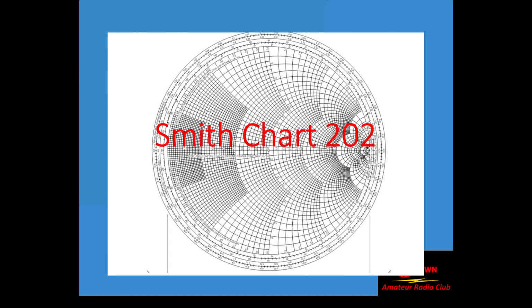So I guess the question is more theoretical, but is that 65 watts or whatever, is that being radiated, or is that just between the antenna and the stub? It's between the... that's what's getting to the antenna feed point. Right. There are still issues in the antenna, as the antenna has its own efficiency. So if I put 65 watts into the antenna and I'm only able to radiate 32 watts, then I've got roughly 50% efficiency in the antenna itself.